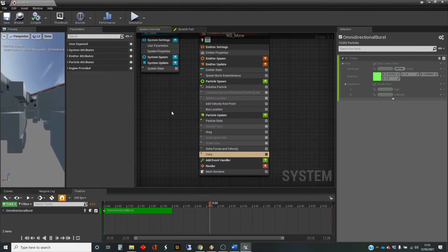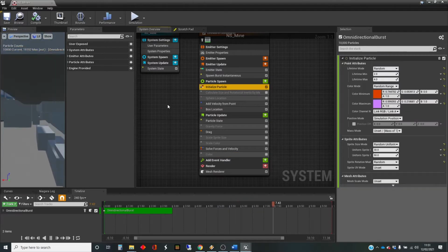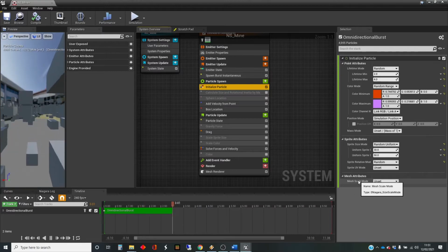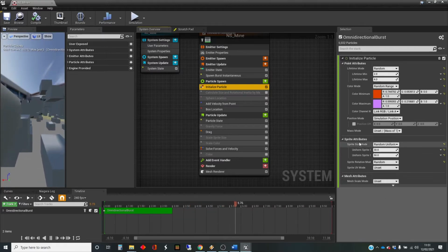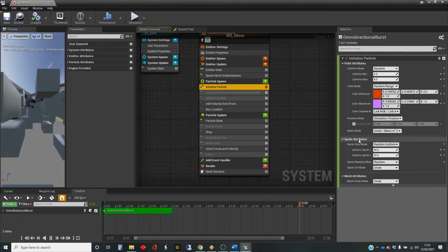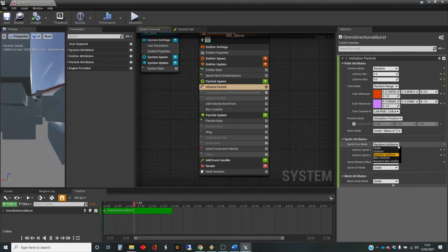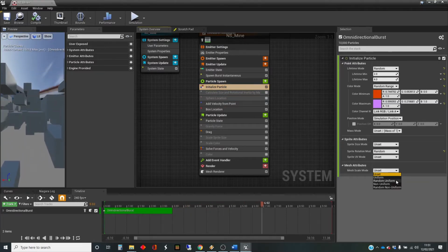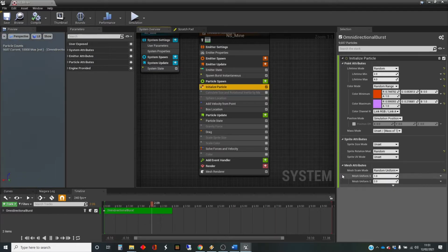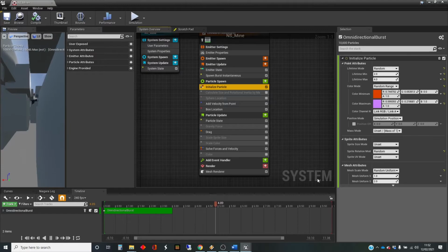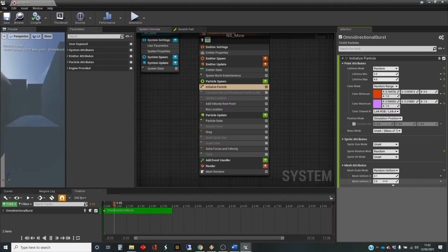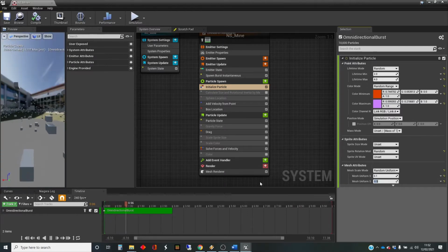And if we go to initialize particle, in a previous video, we mentioned these mesh attributes here. So the mesh scale mode is unset. The sprite attributes are not having any effect anymore. So we can switch that to unset. And we're going to change this to random uniform, which gives us size randomly over a range. And they're quite big. I want to shrink these down, so I'm going to do a size between 0.1 and 0.3, and that's more manageable.